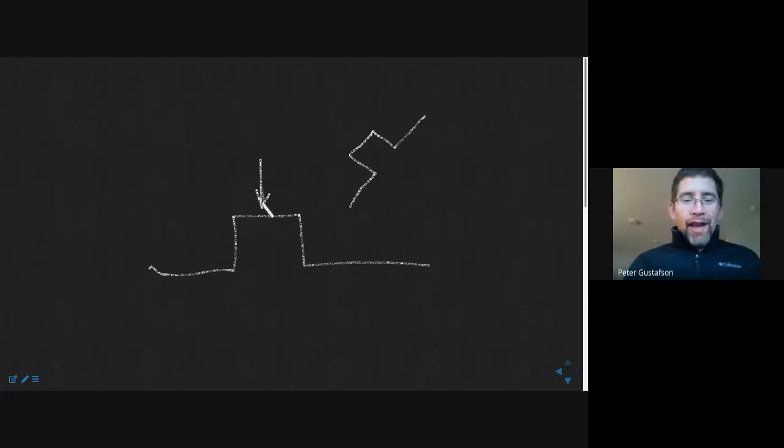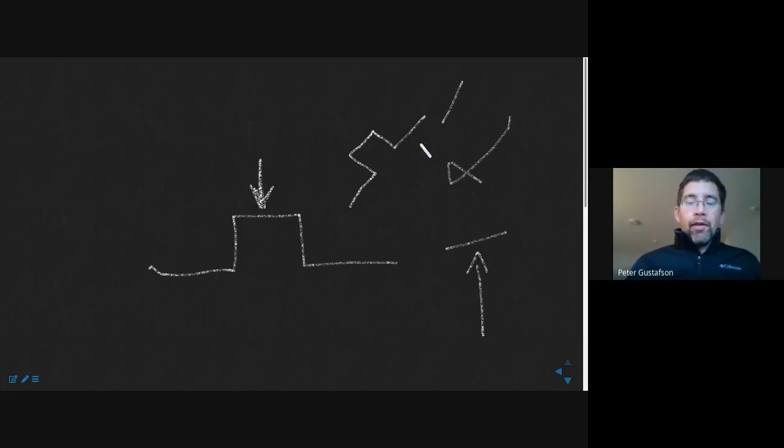So here we go. If you guys can say it makes sense, if I load through this symmetric section, it's going to bend but not twist. And probably if I had drawn an arrow out here, the other way, like this, you might have said, well, yeah, it's going to both bend and twist. There's going to be this angular change here, some alpha, that it's going to twist in addition to any bending that might be present.